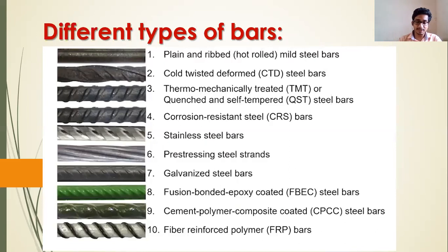If a normal construction bar deteriorates, you can easily see the cracks coming, or the rust stains coming out onto the concrete surface. But in the case of prestressing strands, hidden corrosion happens. There are n number of wires in a strand.